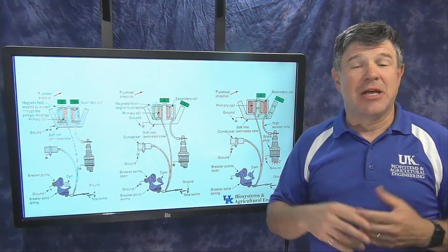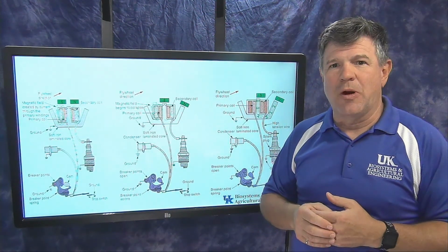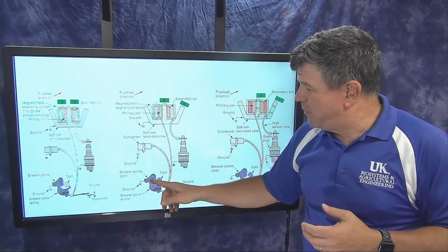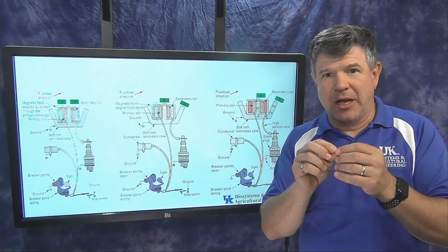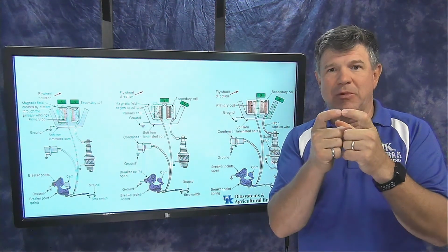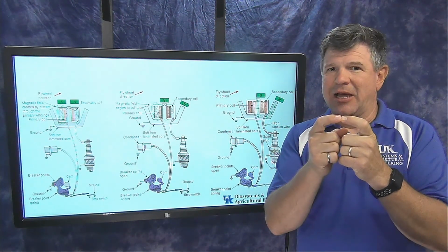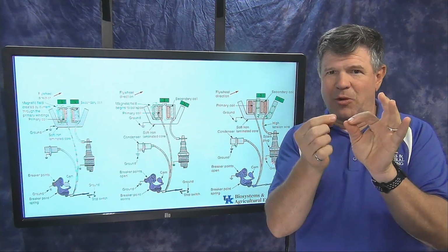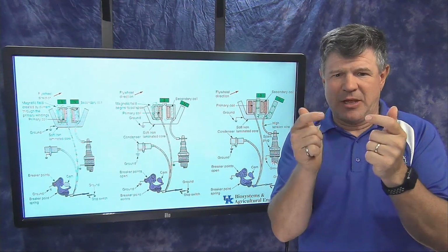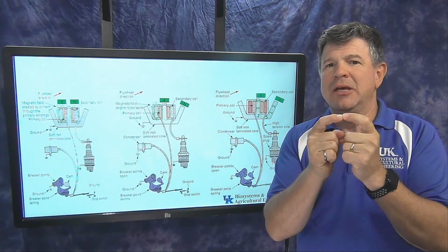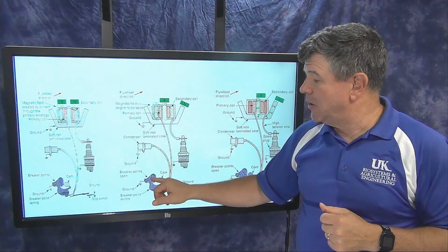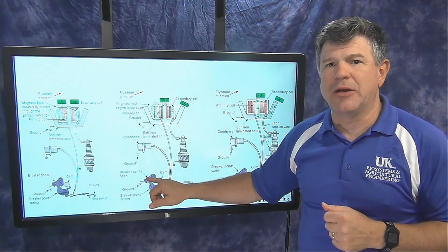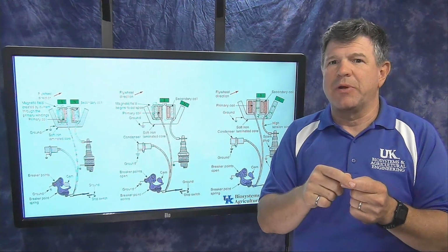And that's one of the things that, when you're doing engine maintenance on an older engine, if you've got points here that are starting to get burnt, so they'll get black, it's almost like you're starting to weld. Remember we talked about how that arc is kind of like a welding arc. So if I start to get little bumps or divots on those point contacts, that's a good indication that this condenser is going bad, because it's not doing its job of protecting the points down here and keeping the spark from jumping across them.